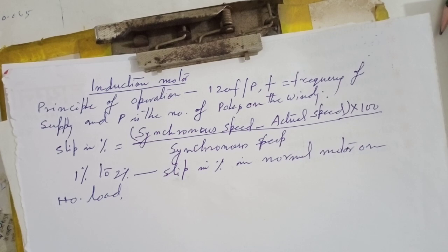In this lecture, we covered the synchronous speed of the motor and the slip in percentage, which is synchronous speed minus actual speed, upon synchronous speed, into 100.